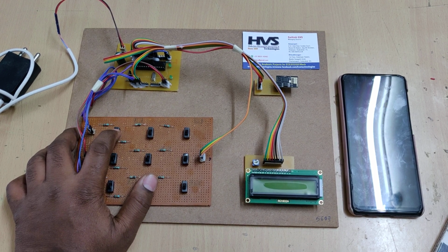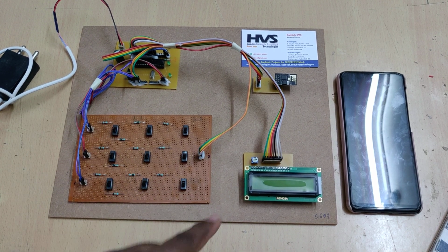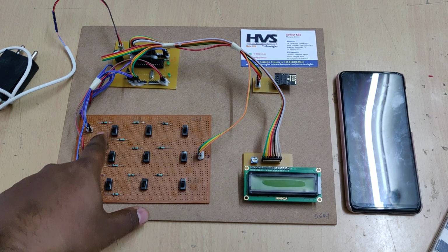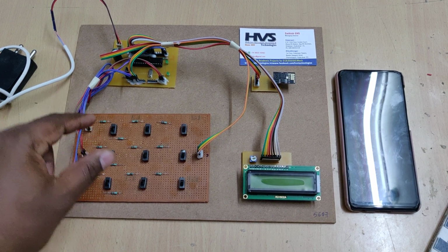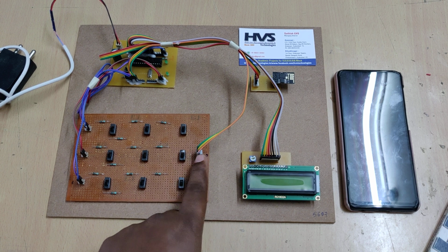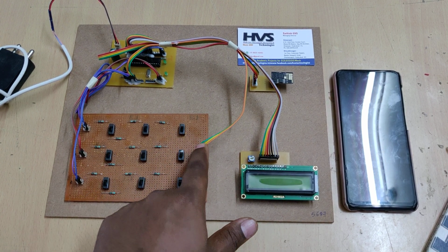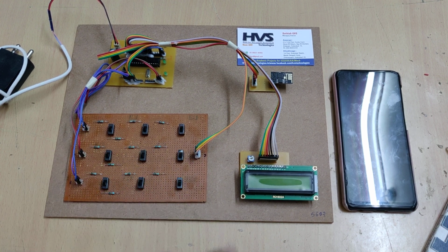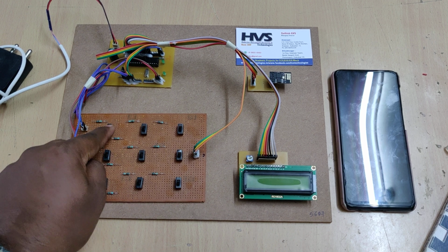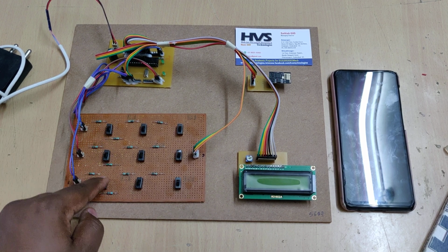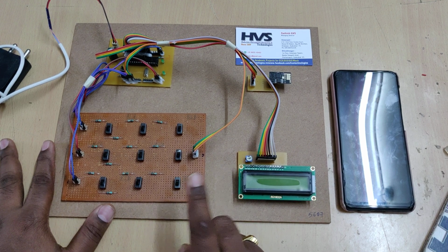Whenever a short circuit happens, the voltage drops. So we need to measure the voltage beforehand. For example, if the wire got shorted in a line to line fault at a distance of 1 kilometer, how much voltage are we getting? If it is 2 kilometers, how much voltage are we getting? 3 kilometers, how much voltage? We need to measure and note down that particular voltage for each particular fault, RY, YB, BR, before writing the conditions.